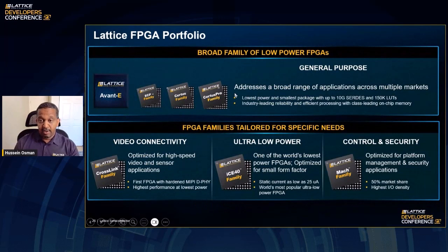Finally, touching on what the offering from Lattice is to enable these use cases. From an FPGA perspective, Lattice has some very special FPGAs, video connectivity on the bottom left corner. These devices are fairly small with hardened MIPI D-PHYs that enable processing or connectivity of image sensors and bringing those image sensors into the system. We can run some additional processing within the system, like an ISP. For the connectivity of video, these devices are perfect.